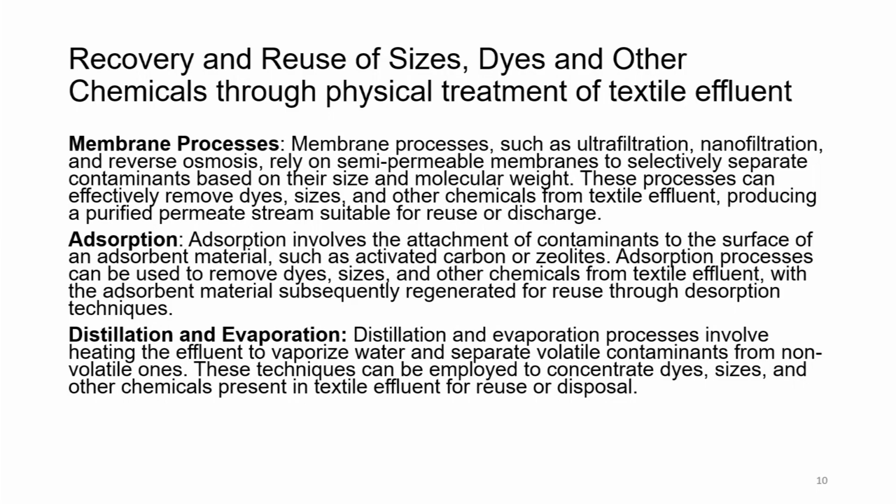So, in adsorption, the contaminant first goes into the pores of the adsorbent material, and later on it is desorbed from the adsorbent material and it can be reused.